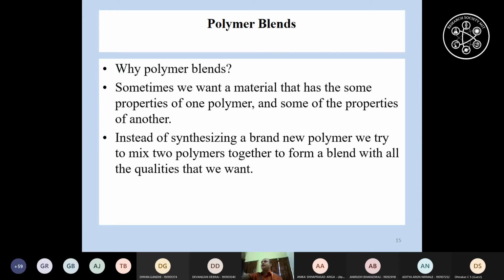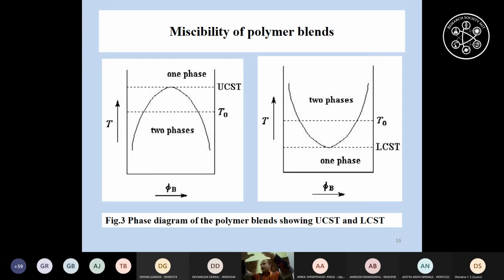Once dissolved, not all compositions will give miscibility. For example, 1% of PVC in THF, tetrahydrofuran, and 1% of cellulose acetate butyrate in tetrahydrofuran. I have to vary my mixture: 100%, 0%; 90% of synthetic polymer, 10% of biodegradable; 80% of synthetic polymer, 20% of biodegradable polymer. Like that, I have to vary my ratio. You might get miscibility in some ratios, while in other ratios it never shows miscibility. Maybe in rare circumstances two polymers in a common solvent might give miscibility, but it won't happen usually.